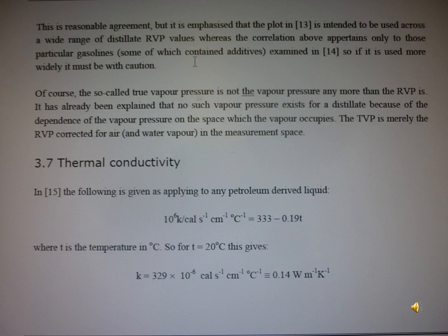A jet engine is a gas turbine, and combustion is continuous in the combustion chamber. This is in contrast to the petrol or diesel engine, where ignition occurs at a required stage in the thermodynamic cycle. Consequently, there is no analog for the kerosene of the octane number of gasoline.